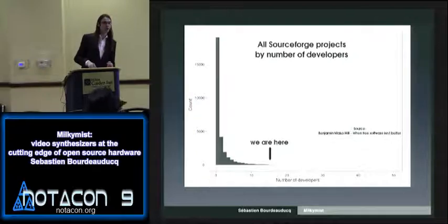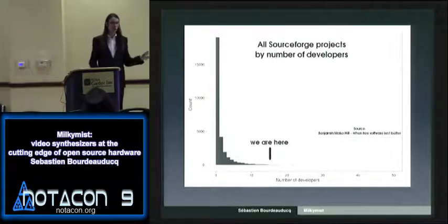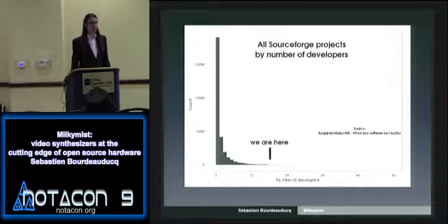A VHDL simulator? Our code is very Verilog, so we don't have any VHDL yet. But of course, we have a lot of simulation, because developing such a system on chip requires lots of code, and you cannot just download it into the FPGA, and when it doesn't work, you don't have any visibility on it. So of course, we need to run a lot of simulation, a lot of test benches, in order to fix all the bugs before they reach the FPGA. Because once they are in the FPGA, you cannot observe any signal which is inside the chip. Well, you can, but it's very difficult. So if you don't simulate it, you don't have visibility on your design, and you cannot fix bugs.